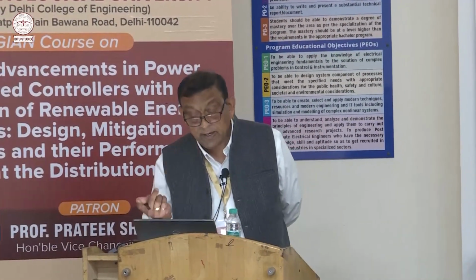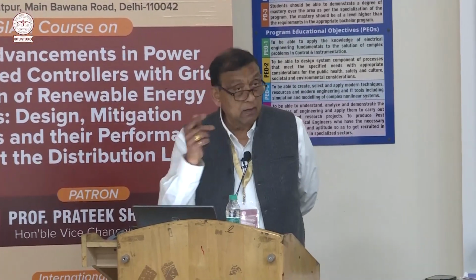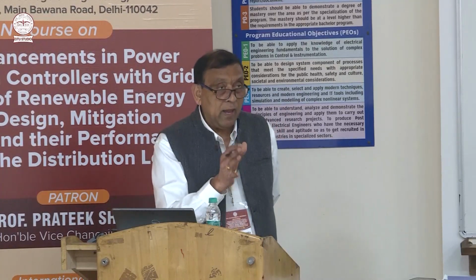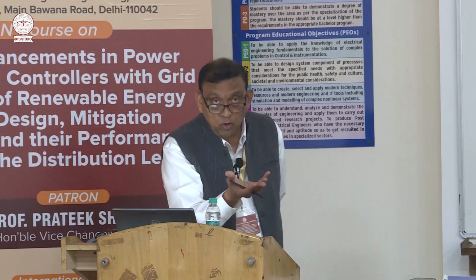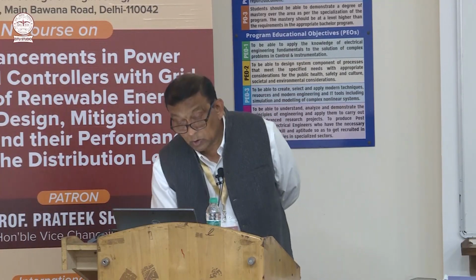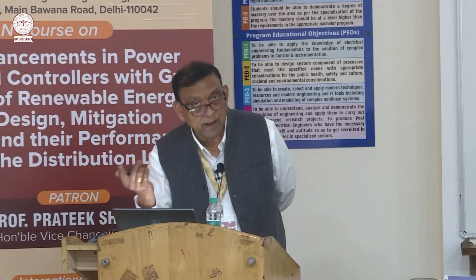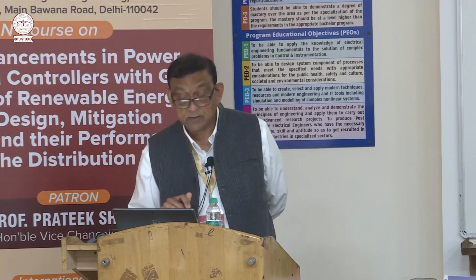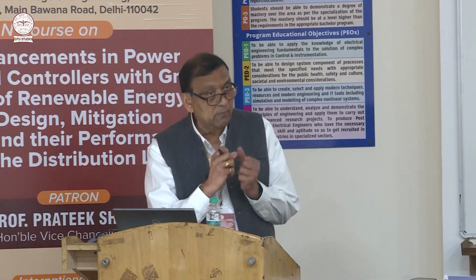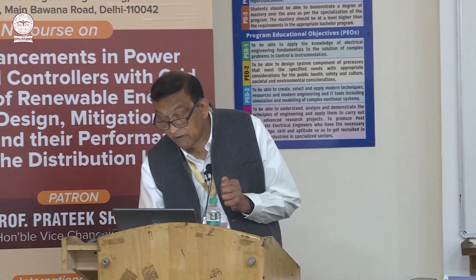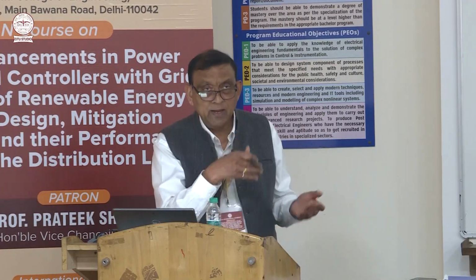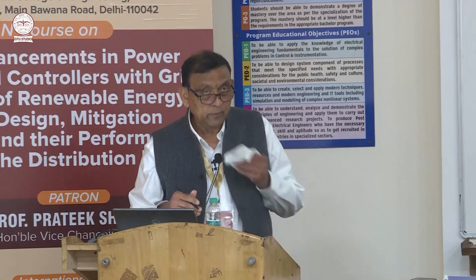If you have a double winding transformer with delta polygon or something, or if you have auto polygon, it will be 30% of the double winding transformer. So that much cost you can save. Cost is much reduced. It is more compact because now it will be smaller, right, with higher efficiency. But the disadvantage is there is no DC isolation because the same winding you are using for input and output, right?